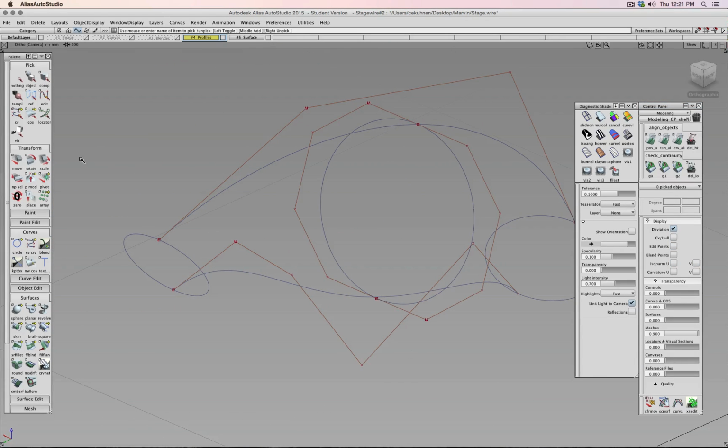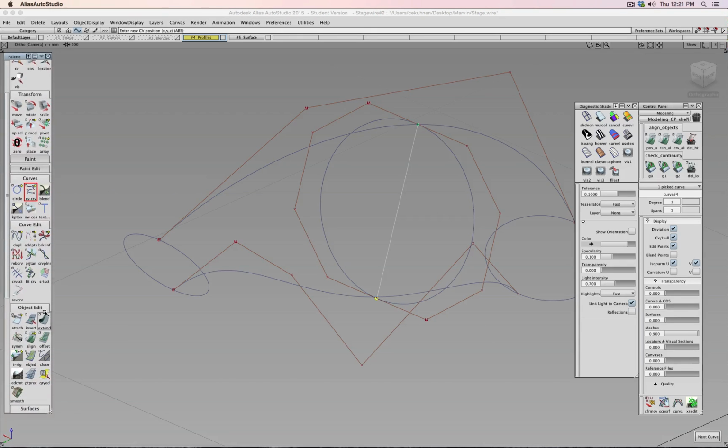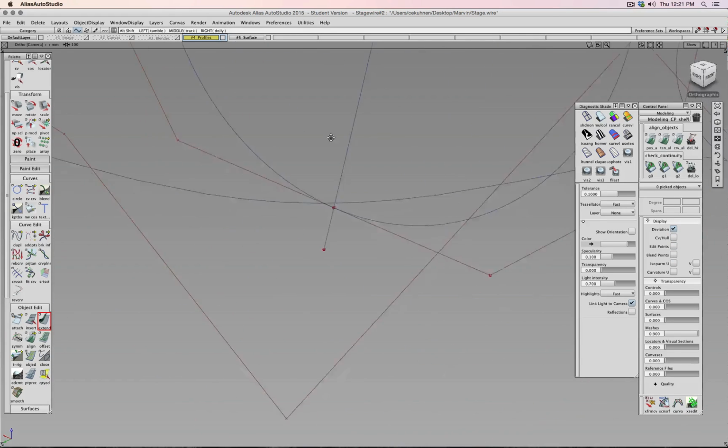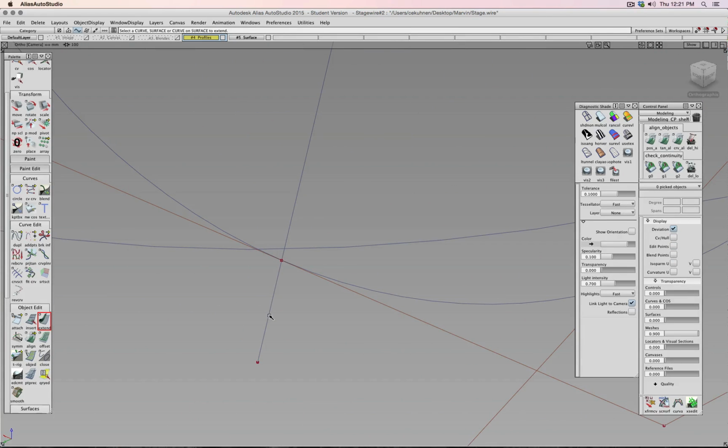Okay, and let me show you a simple trick. Here's Geometry 101. I, for example, make a new line snapping to this part of the curve, snap to this part of the curve. Then I go to Object, Extend, click on this one, move it out there. Why did I do this? This line runs through this point. They're all on the same plane, and it cuts or intersects this curve. So now I could go ahead and say, yep, also project intersections.